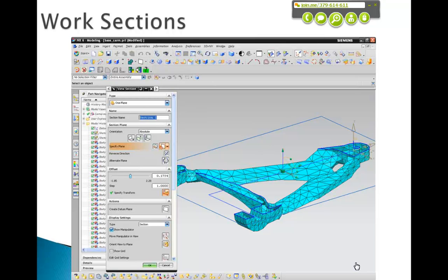Those are only intended to be kind of references as to what the cross-section looks like at this particular cut. If those are put on layer 61, you can go in there and reference those when you go into a sketch, and you can create a sketch that is more manufacturable than these very rough cross-sectional cuts.